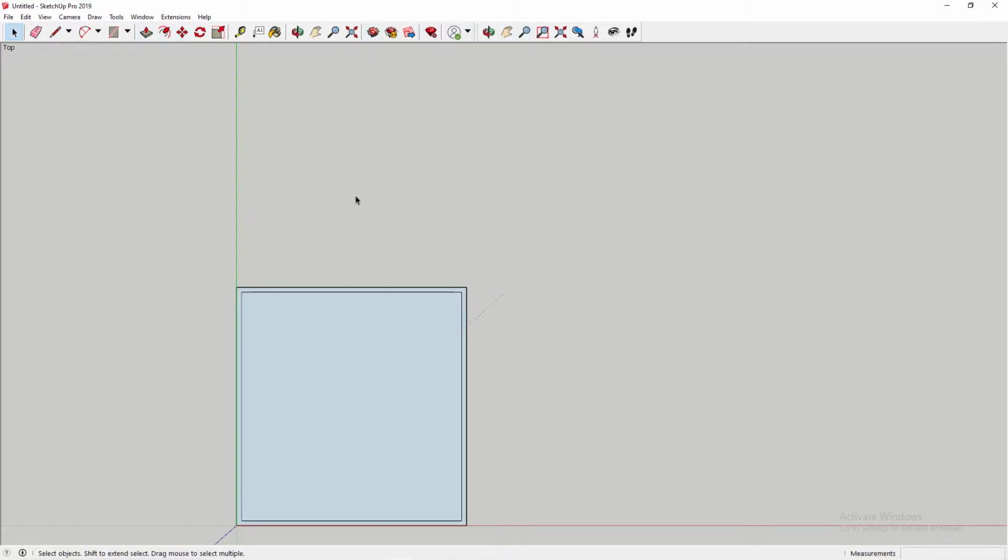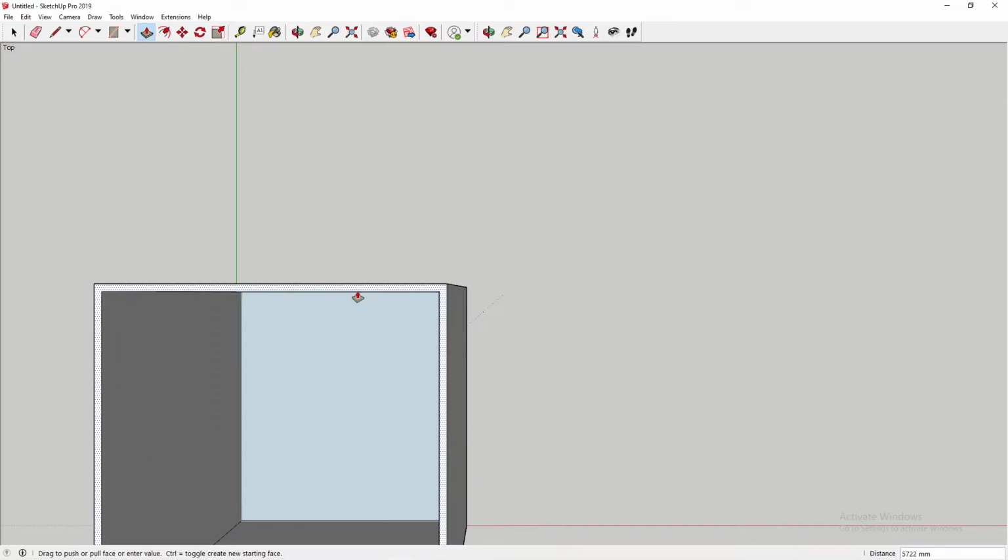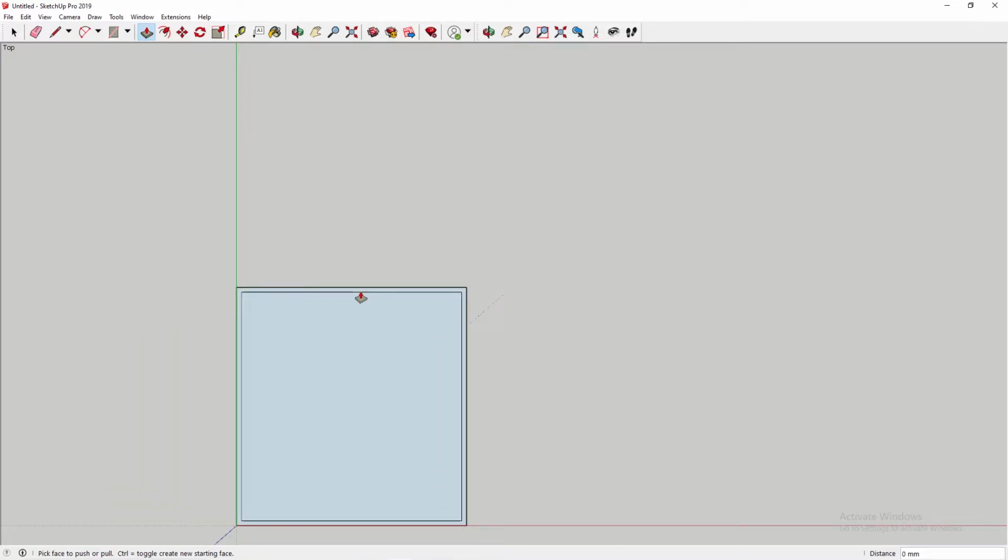So now what we're going to do is, just for this purpose, you'll note that when you make a set, you don't have 4 walls, which is where the push-pull tool comes in. So the push-pull tool can also be accessed by the hotkey of using P. However, as you can see now with the highlighted section, you're creating a complete box, or a box without a roof. So press escape to prevent that from happening.